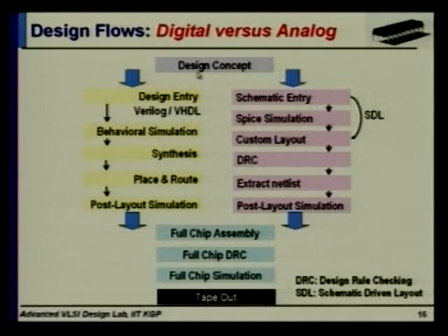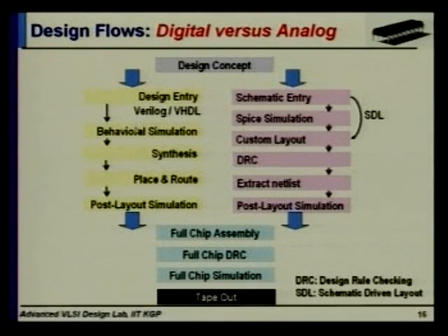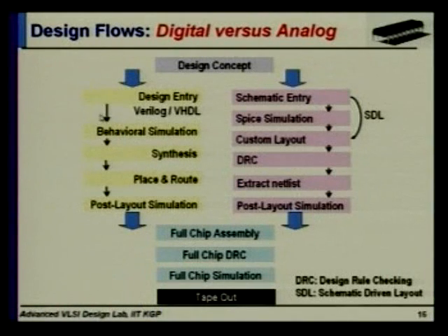In digital design, the entry is in Verilog or VHDL. So you use a high level language like Verilog or VHDL to enter the design, and then you do a behavioral simulation. You simulate that design as a whole to see whether it is behaving in the way that you expect it to. Then there are automated tools for synthesizing that into the gate level designs, and then you do a place and route.